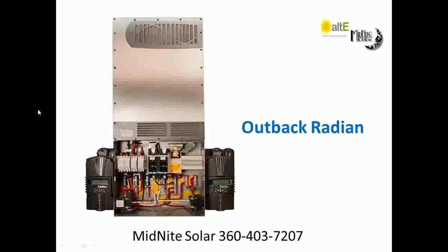But to pacify that, we're slowly working what we call translator modules into the marketplace that will allow our controller to plug into anybody else's inverter. We have the SMA box done. We can now mimic the SMA charge controller. So when you go onto the Sunny Island, start pushing buttons, and go to the charge controller, the Classic actually shows up, and you can read all the data from it. In the case of the SMA system, the inverter has so much technology in it, they wanted control of the charge controller. So the charge controllers do whatever the SMA Sunny Island tells them to do, and it's a very neat system. But we'll be working on that for all the systems as we go.